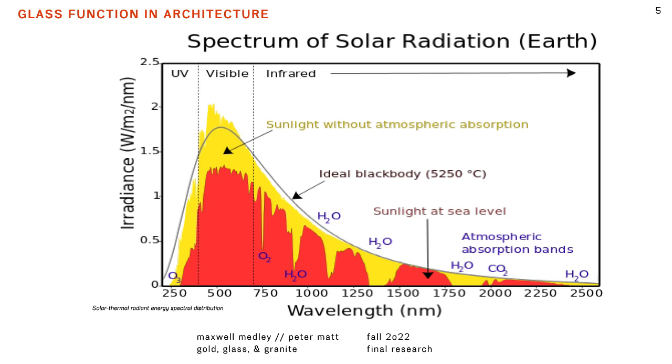Historically, for a glazing system to be energy efficient, it must only control the flow of energy that enters a space. This is typically solar energy and heat transfer from outside conditions. The amount of energy lost or gained by the glazing system can therefore be calculated. Although glazing systems can change the flow of energy into a space, glass alone does not provide adequate insulation to a space. Contemporary glazing units, however, often contain 2 or 3 layers of glass connected in one panelized system.